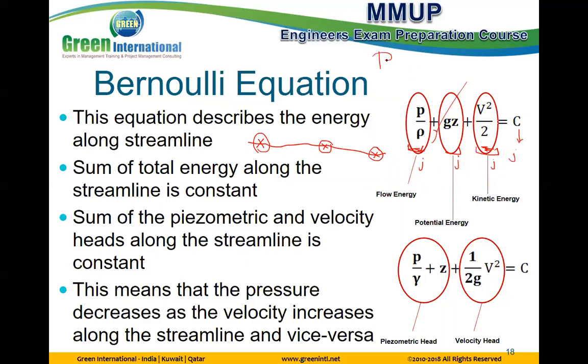You remember P equals gamma H? This pressure equals gamma H, and I tell you this gamma is constant, and we have many devices that measure pressure but in the form of head. This is the same concept. This is the energy equation, or Bernoulli equation, in energy form. Each term has a unit of energy. I can represent this equation the same, typically, not different, but in head form.